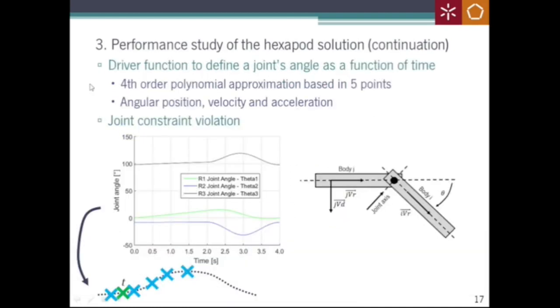In MUBODyn, the existing actuated rotation joint was modified so that it could carry out the desired movements. This rotation joint needs to receive as parameters the desired angle, speed and acceleration for each type of movement. From the temporal evolution of the angle of the joint, for each moment of the simulation 5 points are extracted.